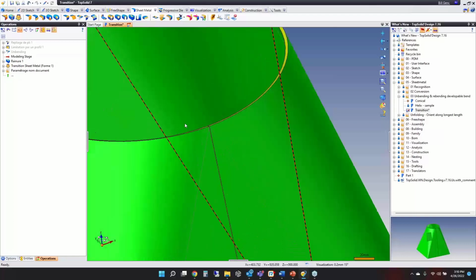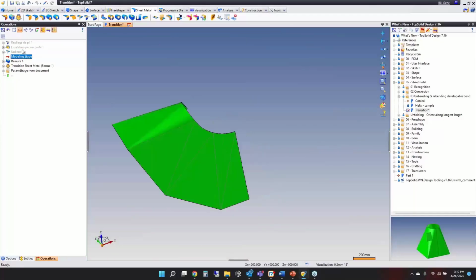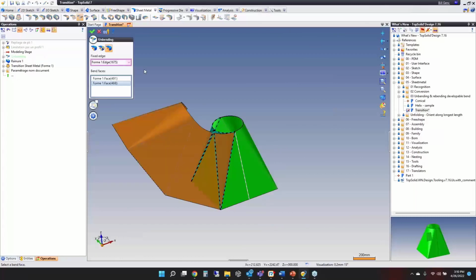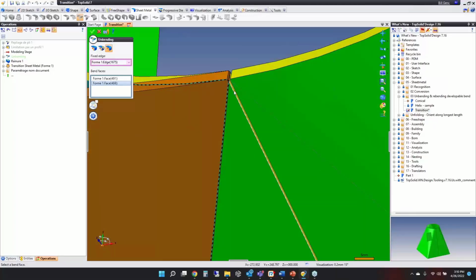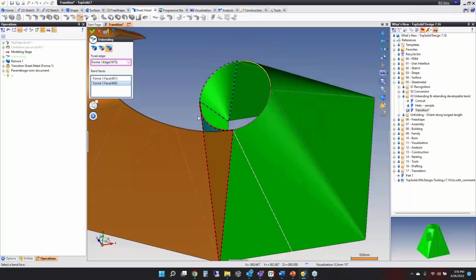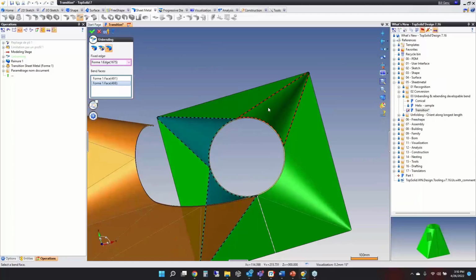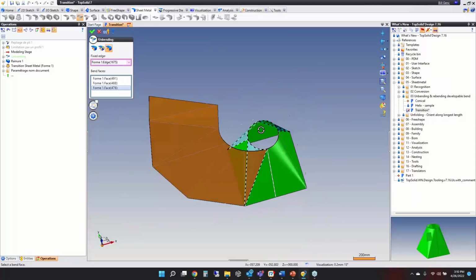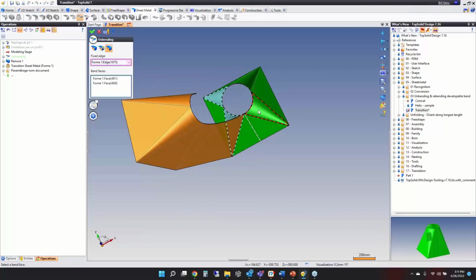Again, I had to split it so that we could create a flat pattern for it. Then we go to unbend it, and I'll edit the unbend so you can see. Choosing my fixed edge, in this case I chose the outside edge of this front face, and I chose other bend faces to unflatten. I could add this one to it if I wanted to, and unroll that. Doesn't really matter. We could add that one. Just unfold and unfold.